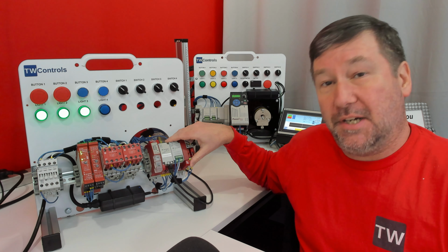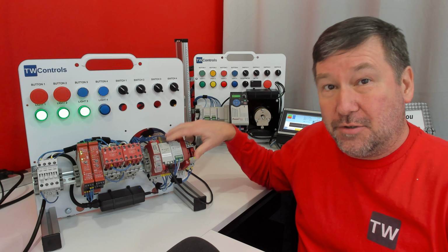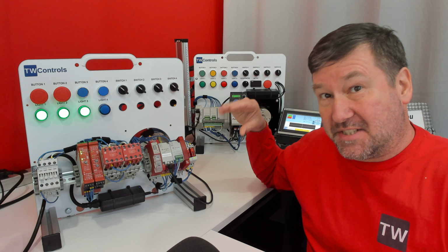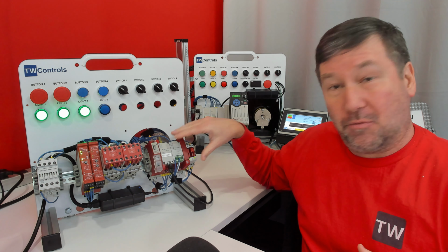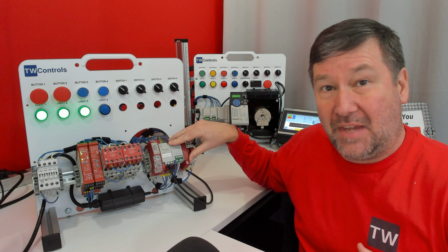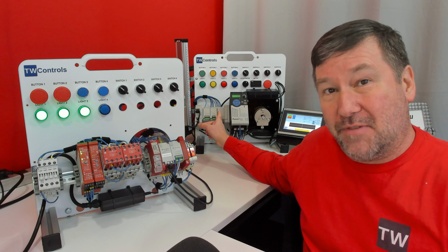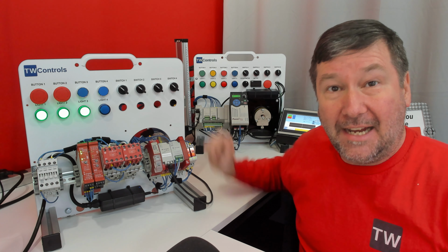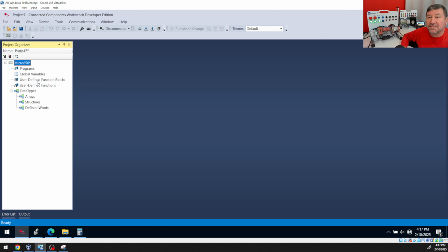In our previous video, we talked about how to put the CR30 into a ControlLogix or CompactLogix I/O configuration so that we could read the status of it. While we can't add it to the I/O configuration of a Micro850, we can use explicit messaging to pull our data across. Let's start with a new Micro850 program in Connected Components Workbench, and let's right-click Programs, Add Ladder Diagram.